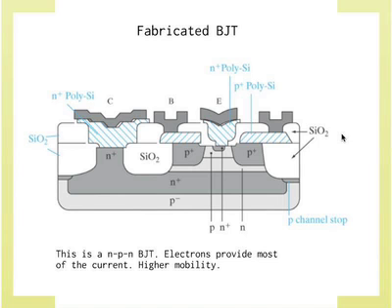The reason to use electrons versus holes typically is because electrons have higher mobility, lower effective masses. You can also have what are called bi-CMOS transistors, where you can have the bipolar junction transistors built alongside MOSFETs. In that situation, you can envision this kind of a configuration with a MOSFET on the other side, with this being the field stop oxide.